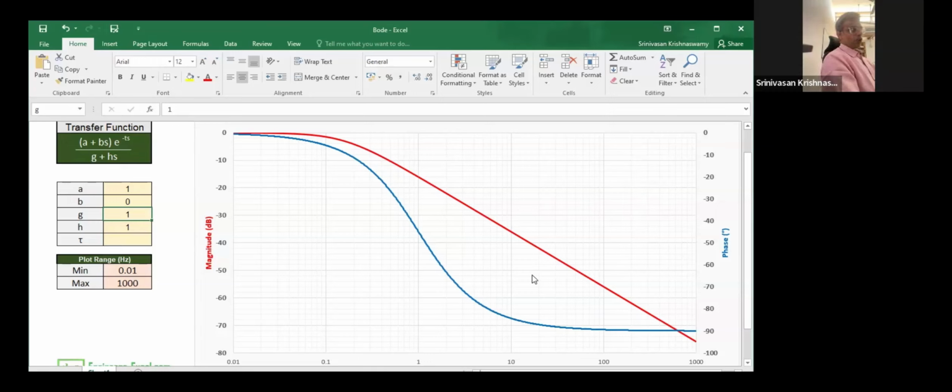So when you have low degree transfer functions, they can be implemented by analog components. And there you do not have the sampling, quantization, and all these other distortions that are introduced. So when you can work with analog, it prevents those distortions from happening. As the degree increases, bringing in so much hardware to implement that becomes more complicated.